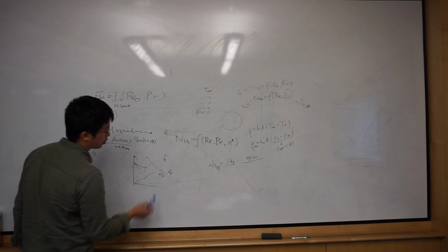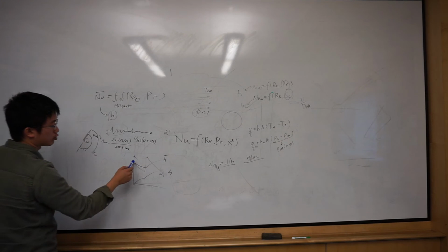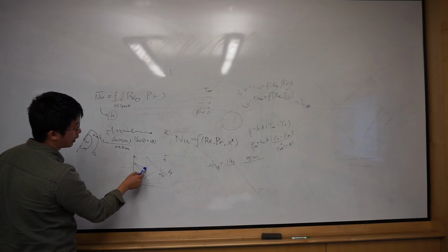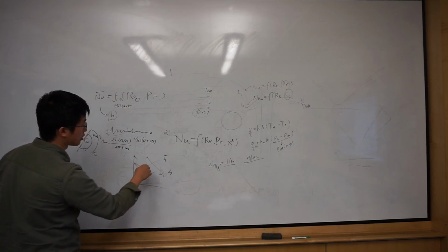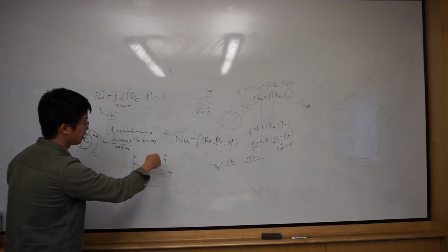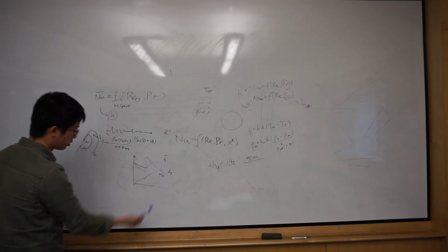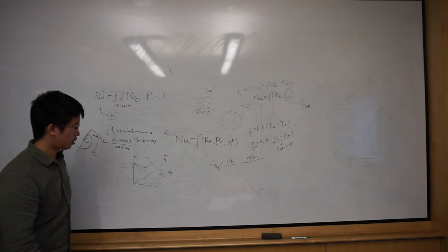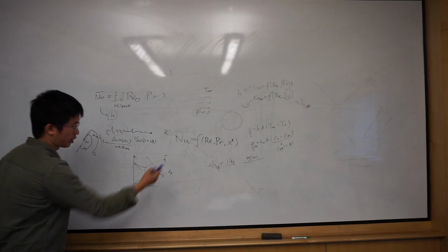But the average from the leading edge to that location, for the laminar zone, stands on top of the local one, and because it's an integral, it doesn't jump, but changes curvature. It's not smooth, right? And the Nusselt number looks like this. And actually, the boundary layer also looks something like this.